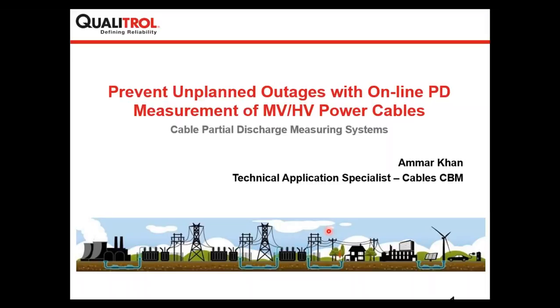Actually, you are all talking about neural network technology, or support vector machine, or fuzzy logic technologies to classify between partial discharges and noise. From Qualitrol's perspective, we have been using artificial neural networks for our other expert analysis systems, but for the cables, we are only discriminating between noise and partial discharge activities. So far we are confident with the same technology, and we are getting very confident results.